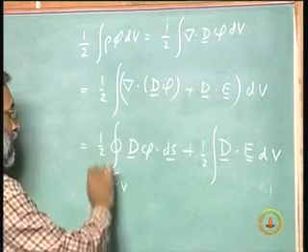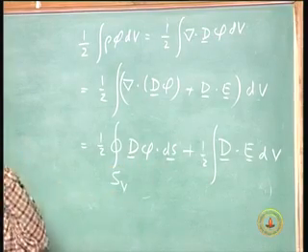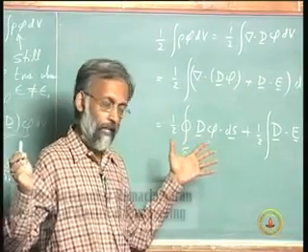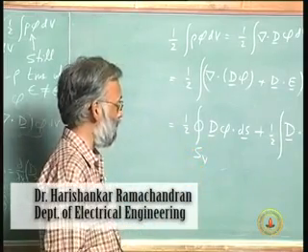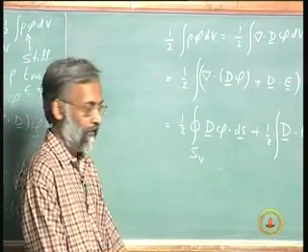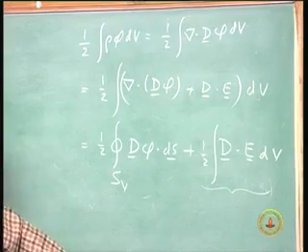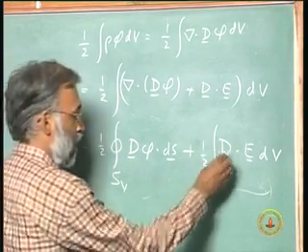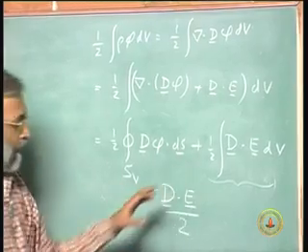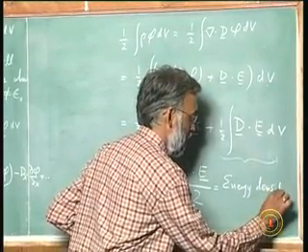Now, what we do with this surface integral depends on what device we have. If we have a capacitor, the surfaces are in fact the metallic plates, and it is not true that phi goes to 0 there. But if we are talking about charges in free space with some materials present, then phi goes to 0. So, we can't actually throw away the surface term anymore. The surface term can be important, but this piece is the piece we commonly associate with energy in the field. This quantity d dot E over 2 is like energy density in the field.